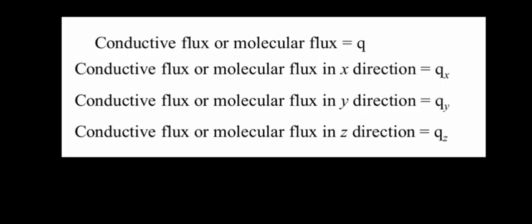So Qx is directly proportional to minus dou T by dou x, Qy to minus dou T by dou y, and Qz to minus dou T by dou z, where T is the temperature, and the proportionality constant is the thermal conductivity of the fluid. Therefore, the conductive heat flux vector Q represents the rate at which thermal energy is being transported through the fluid due to these molecular interactions driven by temperature differences. Even if the bulk fluid is not moving, heat can still be transferred from a hot part to a cold part through conduction.